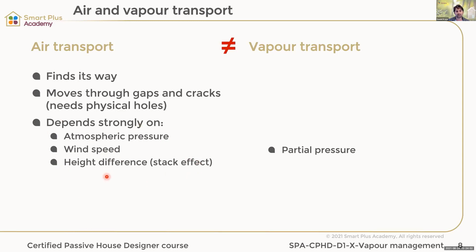So if you're building and designing high-rise buildings, because of the stack effect, you already need to build really, really airtight. So all these facade systems for high-rise buildings are already really, really airtight, and they normally work on that. And with airtightness, really, you want to have a balanced heat recovery ventilation system.